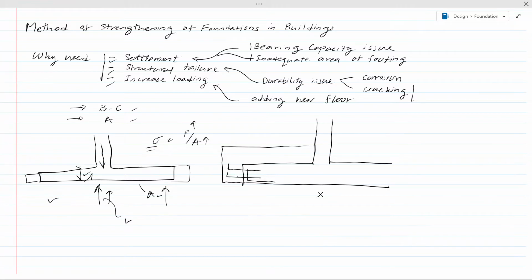If you have T10 bars, 10 millimeter bars, we have to accommodate the required anchorage length, and also have sufficient anchorage there. For 10 millimeter bars it could be 100 millimeter, but in general it's better to go to a higher anchorage length, because you are not aware of the bottom reinforcement arrangement of this footing. This reinforcement might be straight, sometimes you might not have a bend there. Therefore it's better to have adequate anchorage there. I suggest an anchorage length between 150 to 300 millimeter would be better.